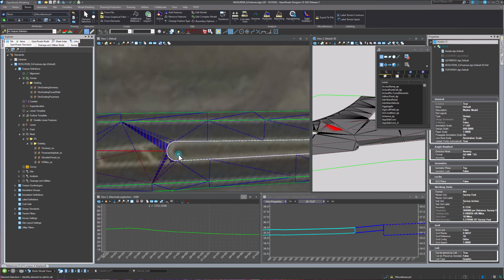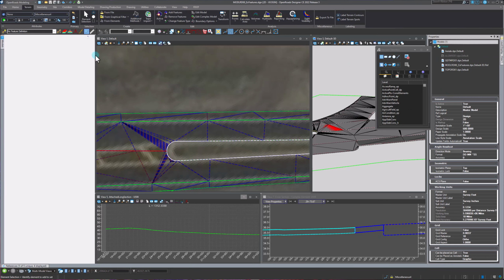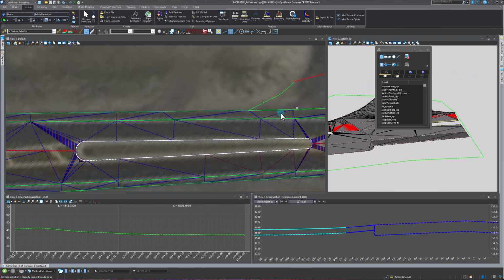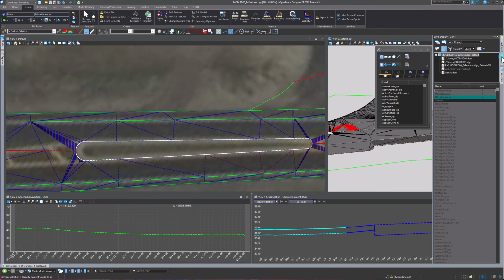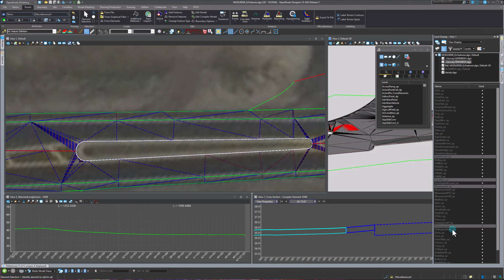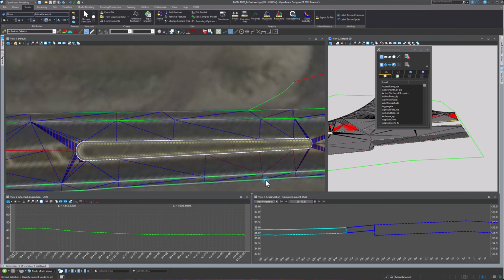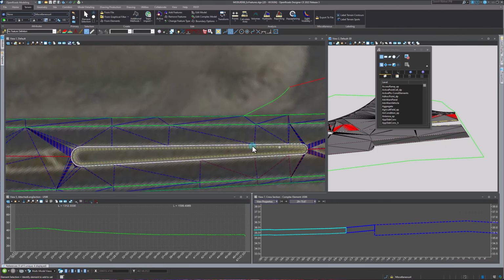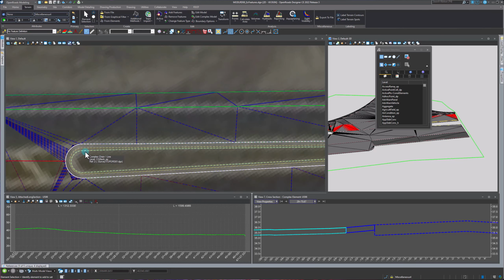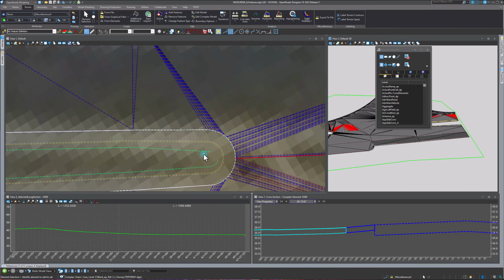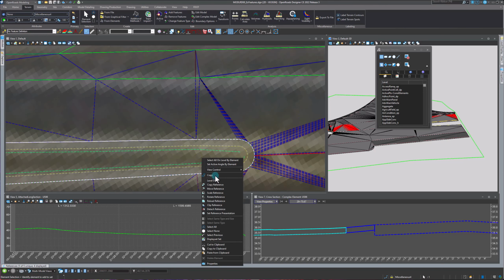So curb is a little bit different than all of these other things we've been doing. We've basically been making terrains and applying surface templates to them. So I'm just going to collapse these so we have a little more space here, because we've done looking at volume options and stuff like that. From the topo, I want to make sure that all of my curb levels are on. So CG, face, EP back, let's turn those back on. What I'm really interested in here is this curb and gutter back line right here. Let's go ahead and copy that in.